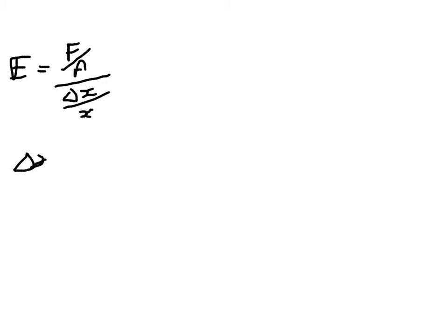So you should have had a go at the question about the steel wire of length 3 metres that's being stretched, and you've been asked for the extension of the wire and its thickness when it's under tension. So obviously, if it's being stretched, it's going to be thinner. So that's your Poisson ratio. How much is it being stretched? Well, that's using your Young's modulus from the previous video that we talked through. So we know that Young's modulus is force over area over delta L or delta X over X. So delta X equals Fx over EA.